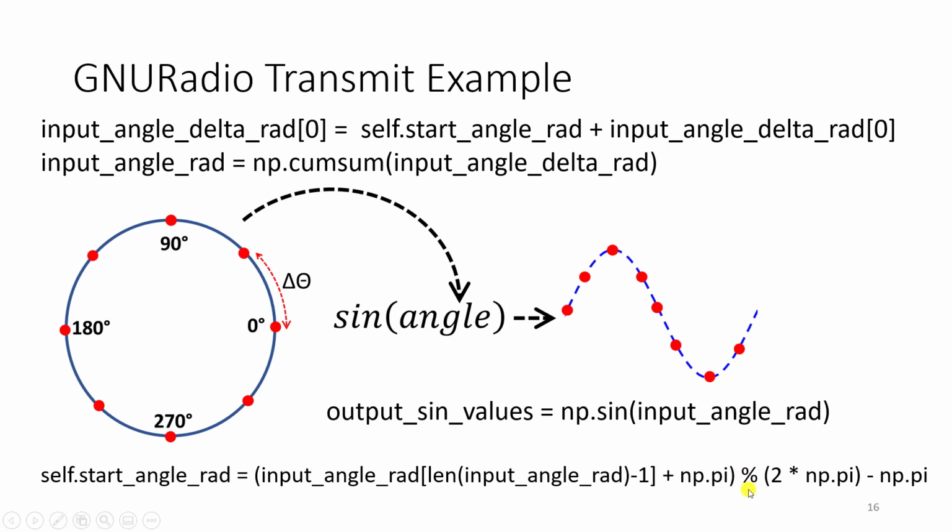And so all we then do, because one of the numerical stability issues that we have in a practical implementation is the wrapping around the circle. So what happens after we've completed that first cycle of the waveform, because as you recall the chirp had multiple cycles in it, when it wraps back around here, what we need to do is wrap around that phase.